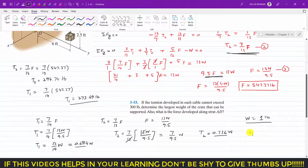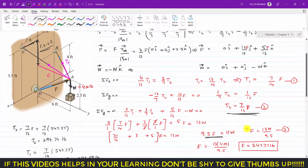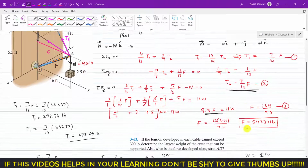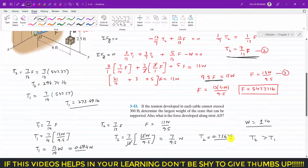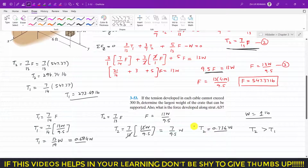This means that the T2 tension will be greater than T1, and T2 is the tension in cable AC. So cable AC is carrying the maximum tension. Now if we assume that T2 is under maximum tension, then we can find W using this equation.